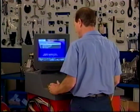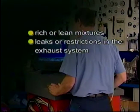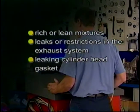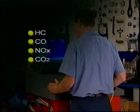Exhaust gas analyzers can be used to diagnose several different conditions such as a rich or lean mixture, leaks or restrictions in the exhaust system, and even a leaking cylinder head gasket. Exhaust gas analyzers measure the amounts of HC, CO, NOx, CO2, and O2 in the exhaust stream.